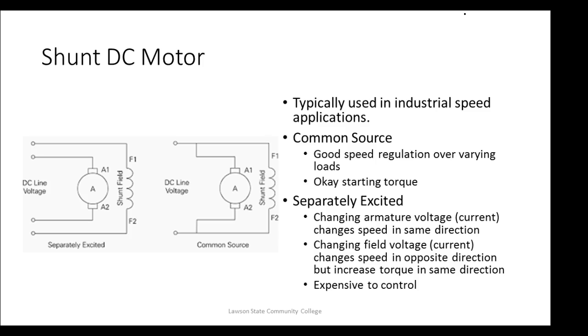So this is a type of motor called a shunt motor. And notice here we use 2 electromagnets. We use the field as an electromagnet and the armature. So this is the symbol of an armature of a DC motor. If you ever see this circle with these 2 little blocks on the side representing the brushes, that's the armature of a DC motor. That makes sense?